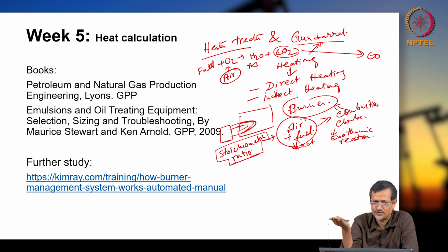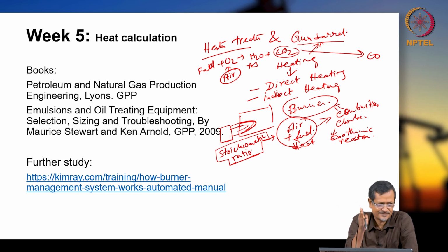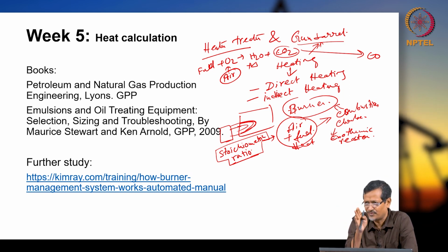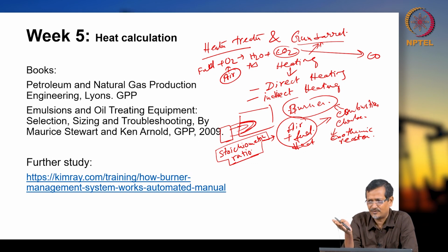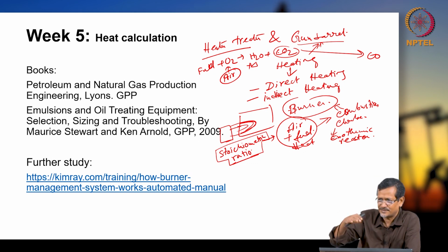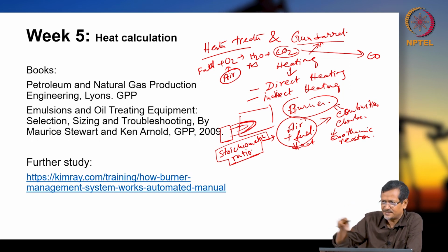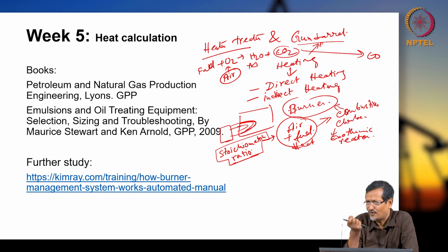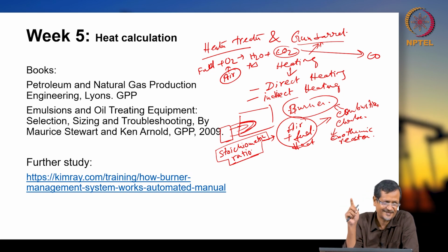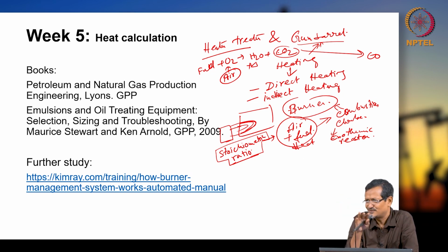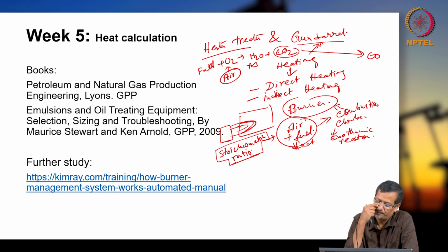With less fuel, there is less heat, so the temperature will go down. If it is still not controllable, completely cut both oxygen and fuel, then check where the problem is. Maybe the water level is going down, or there is another problem in the piping system, or a leakage, or unnecessary fuel is going at a very high rate, or the oxygen supply is lower. All these things you have to check, okay.